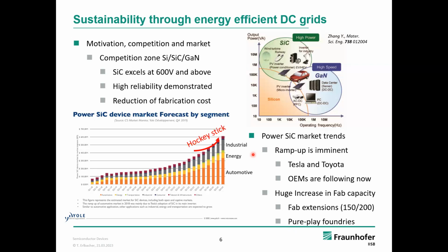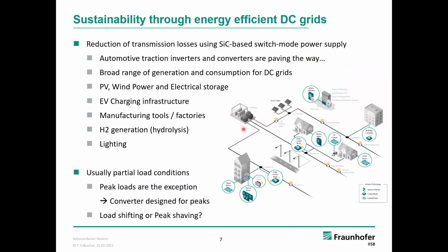And then, of course, the hockey stick at some point will come to an end, and you have to consider yourself in competition with other companies and industry that might have more efficient devices, smaller devices, more cost-efficient devices, which then will also be the door opener to apply silicon carbide in applications where you don't get the great benefit that you see now for electric vehicles, but then also for static energy conversion, for instance, PV, wind power, electrical storage, where you already see, for instance, silicon carbide Schottky diodes being used.